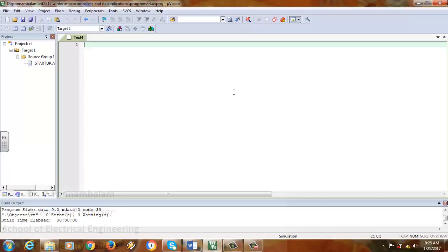As I have already told you, it's like code to internal memory. So here the code memory address will be accessed through DPTR only. So again mov DPTR, comma, hash 4500h.